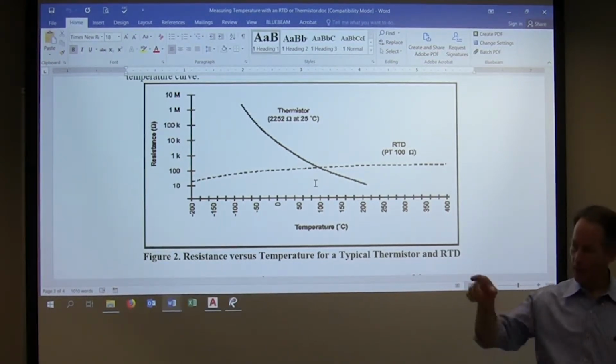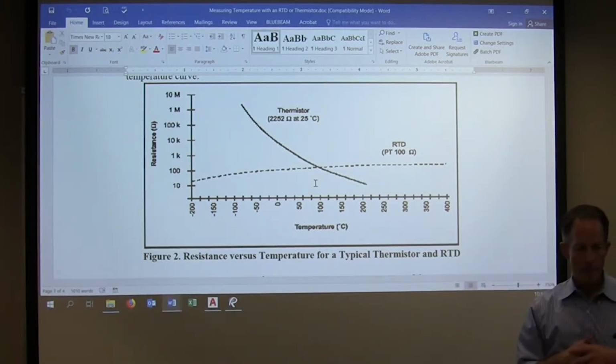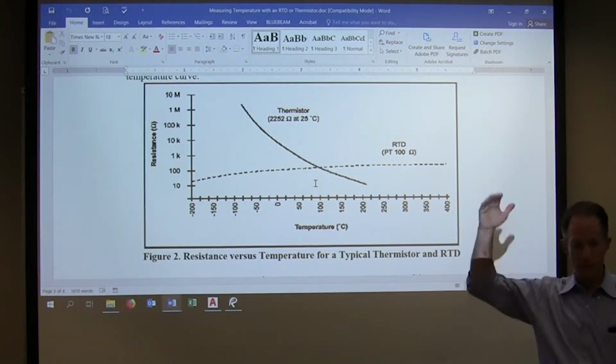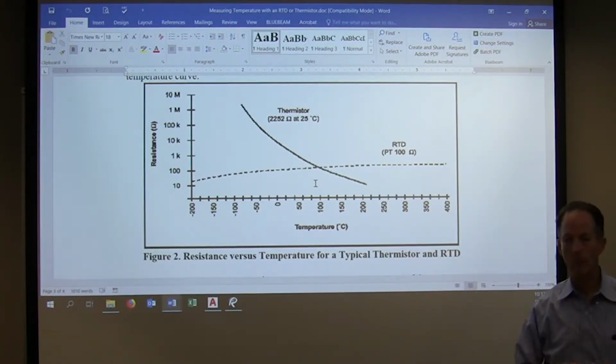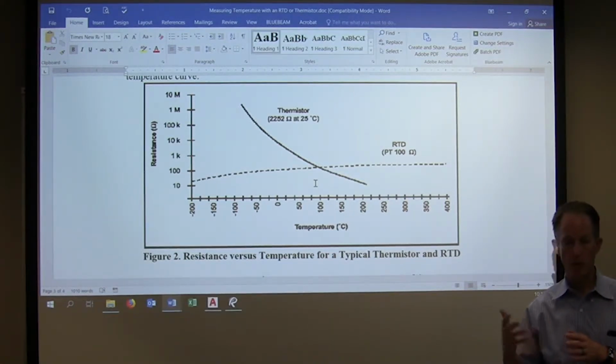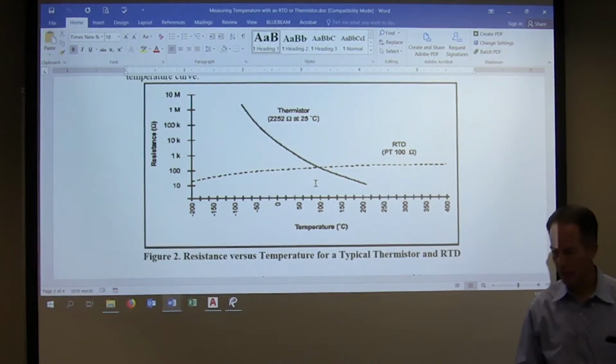So there's that equation on the bottom of the board there. PV equals nRT is the gas law. Pressure goes up, temperature goes up. They're directly proportional to each other. They use those, and that pressure can sometimes trigger a switch, but it also sometimes will operate a transmitter, right? And that transmitter could be voltage or it could be milliamp, depending on what the application is.